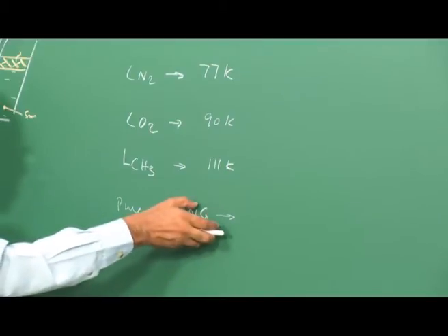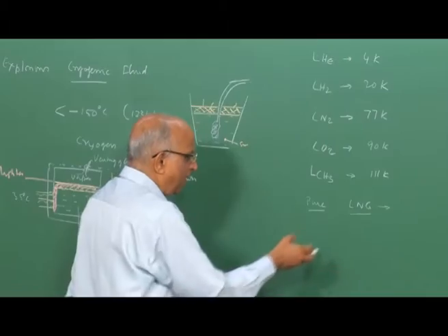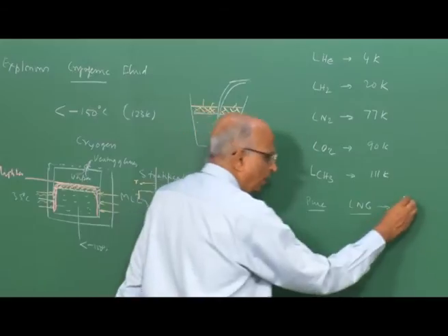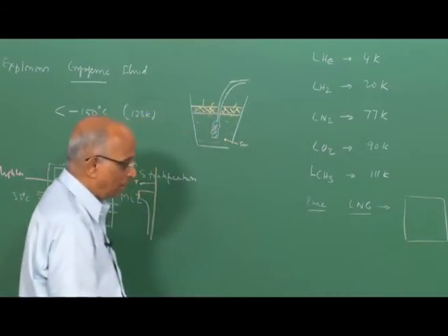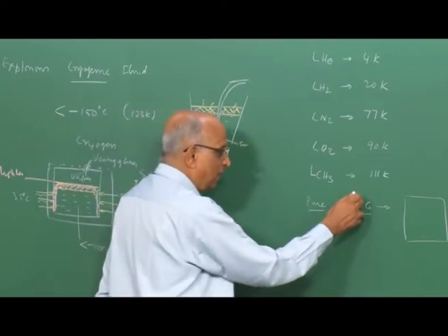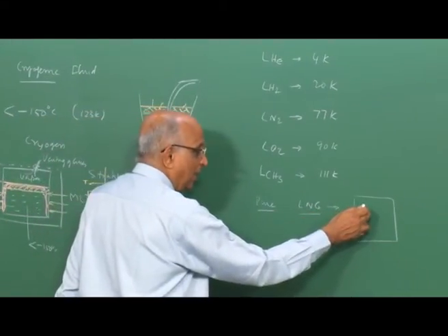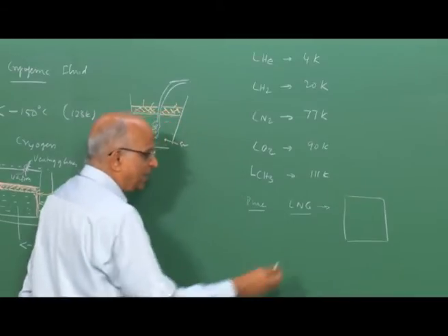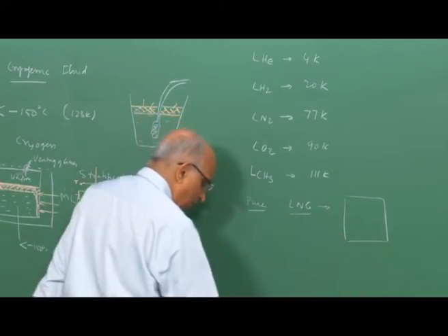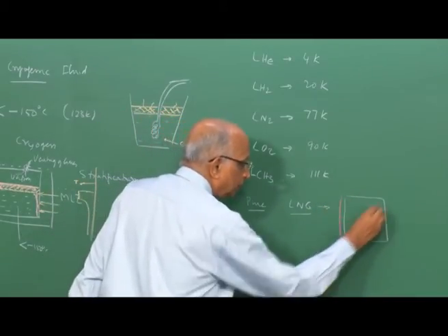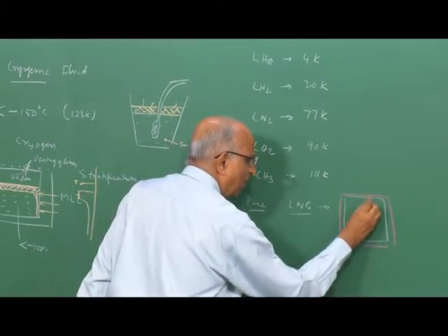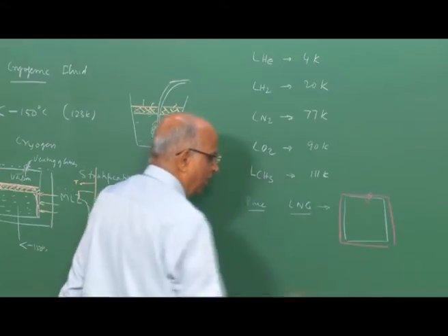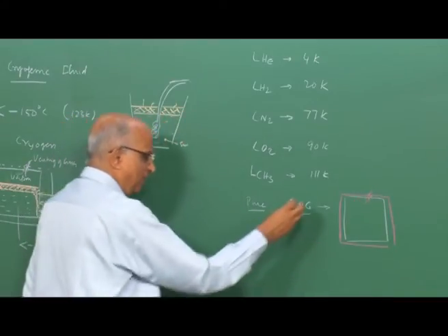Not only that, it is also transported in pipelines, and it is also stored in tanks. For instance, off Cochin Harbour, we get LNG, we then store it in huge tanks, and these tanks are again, as I say, well insulated with a vent valve, such that if vapor is being formed, you occasionally vent it out. And what happens?